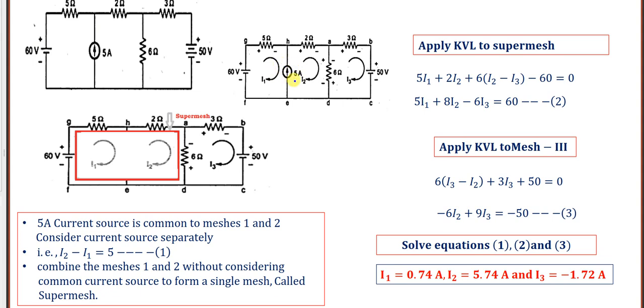Here the 5 amp is the current source. It is shared by two meshes, I1 and I2. Mesh 1 is this, mesh 2 is this, and this 5 amp is in between these two. So I can combine these two and form a super mesh. You can see here the red color; that is the super mesh. And I can apply KVL for the super mesh. In the super mesh path, you see resistance and voltage, so I can write KVL for the super mesh.